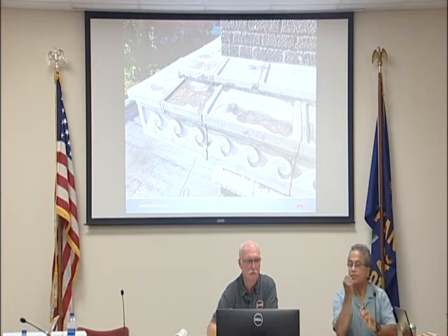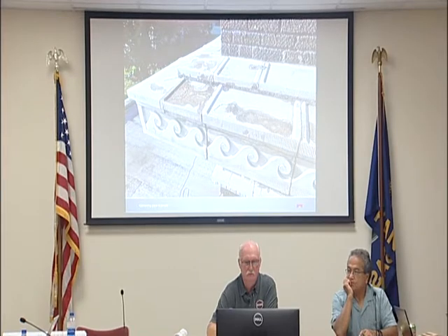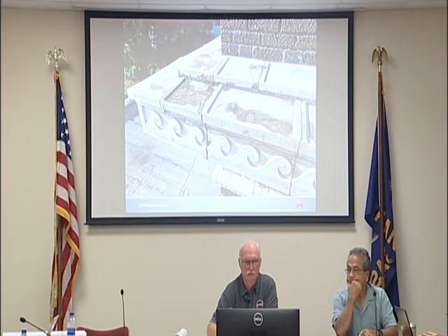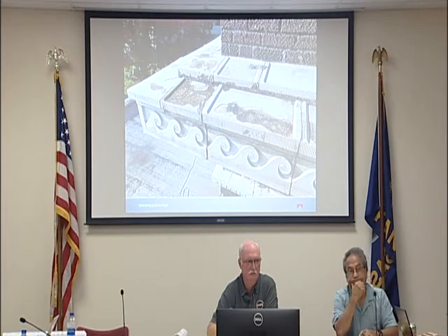And this is just one of the photos from our earlier presentation showing the kind of deterioration that we were finding. This is at the terracotta cornice, where you can see that over time, open joints above in the masonry and in the terracotta itself have allowed water to get into the system and cause spalling of the glazing. So in this situation, our document set's covering repair of the glazing with a glazing replacement product and installation of more durable sealant joints at all of the skyward facing surfaces on the cornice, as well as then full repointing of all the other masonry joints in the cornice.